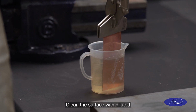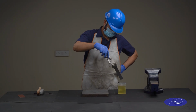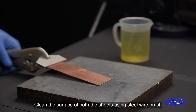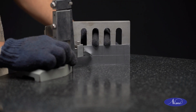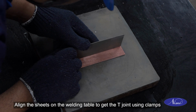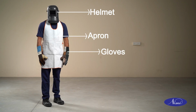Clean the surface with diluted hydrochloric acid to remove oil, grease, paint, etc. Clean the surface of both the sheets using steel wire brush. Mark the midline of the MS sheet using vernier height gauge. Align the sheets on the welding table to get the T-joint using clamps and support. Wear safety apparel.